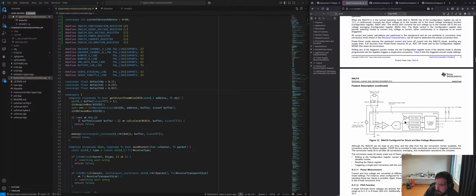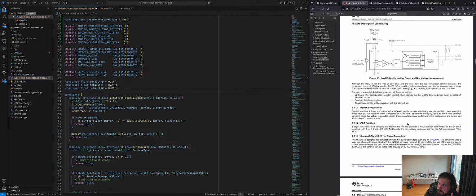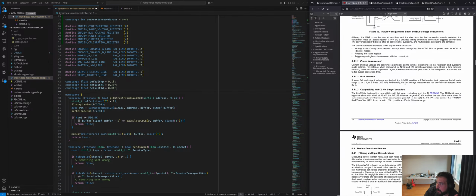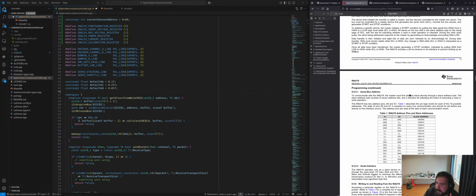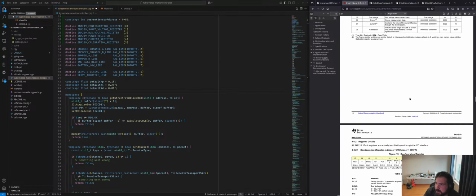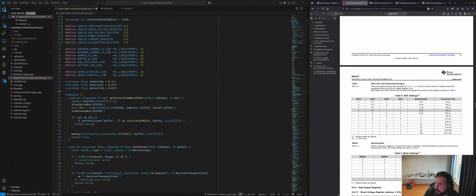Basically, there's a multiplexer that flips between measuring the shunt and measuring the bus voltage. So we want to make sure that we can do two converter measurements per our sampling frame. So we probably want to run in that 7 or 8 millisecond mode, 8.5, because it'll be able to do 16 samples averaged.